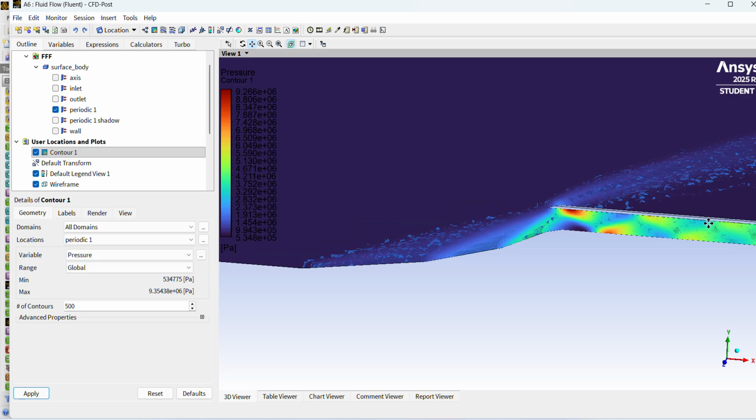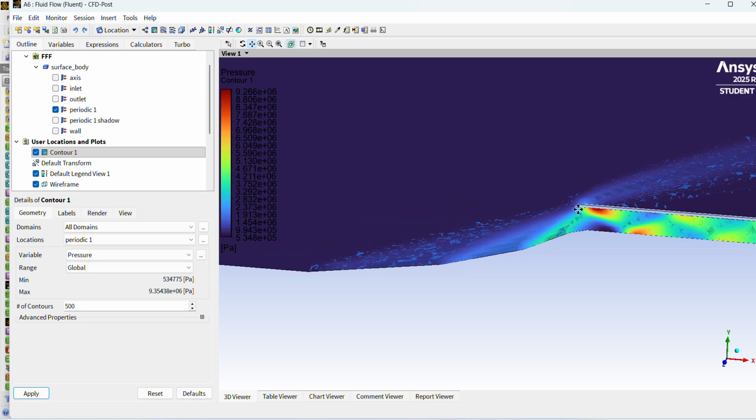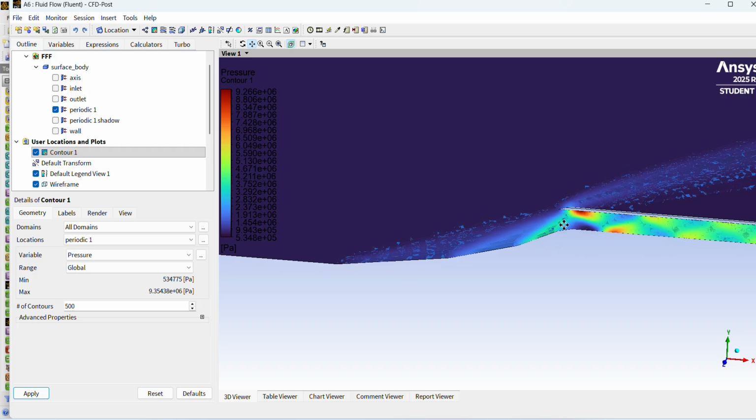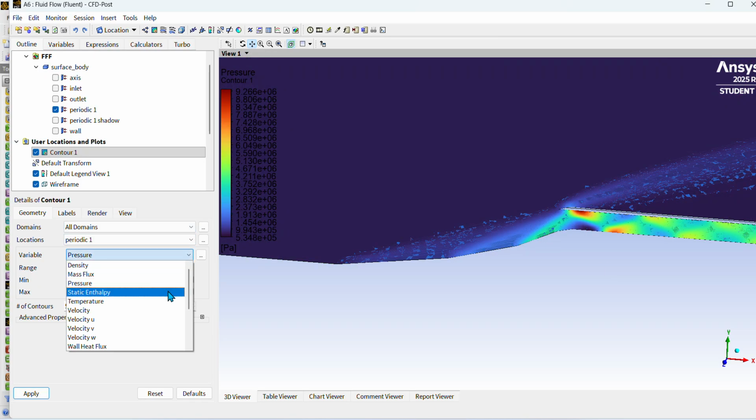Also you can make sure that these oblique shocks touch the cowl tip exactly. So we will adjust the ramp 1, ramp 2, ramp 3 angles, their positions, and the distance between the first ramp and this cowl tip. These dimensions we will try to change. Then I will see the velocity contour.